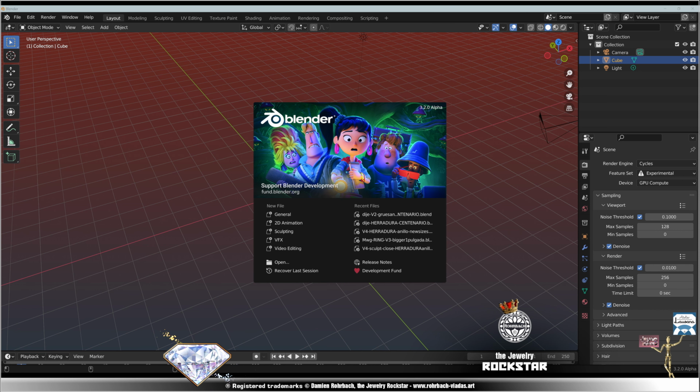But now we need to adjust this bezel to the prototype shape. So let's go and make an Alt C to apply the Boolean, and let's go to edit. So what we can do here is we can take these vertices and let's do an S Z. We need to adjust and also scale like this.